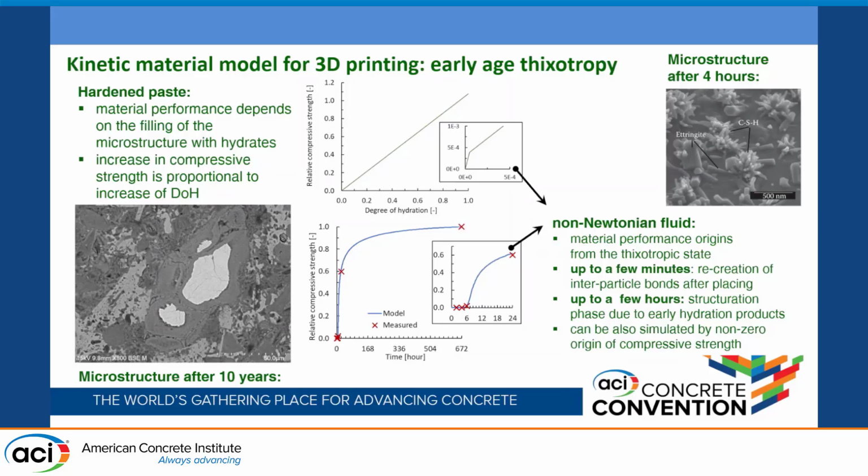And of course, there is the important thixotropy state, which we try to address with our solid material model. Maybe it is not the right way to do it, but basically we are playing a trick: even though the hydration is not there, we introduce some initial compressive strength to be able to consider this initial strength of the material, which is due to thixotropy. Later on it is changed to the real strength gained from the hydration products.